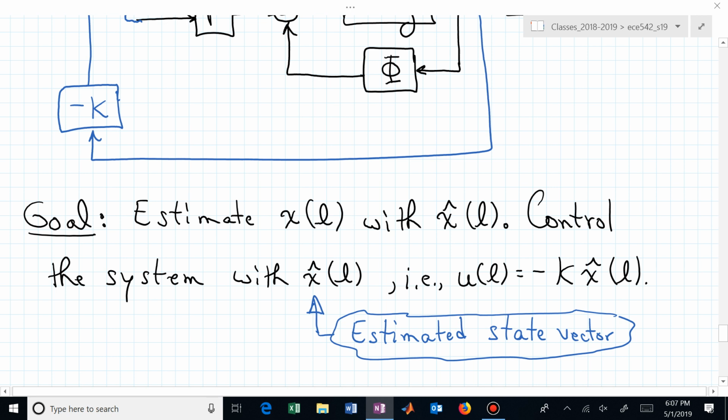You'll hear it called an estimator, an observer. How do you select the speed of that estimator if you're putting all of this together and you want your closed loop dynamics to be influenced by phi minus gamma k, the K matrix? It really is problem specific. I can't tell you make it a factor of 5 faster. I can't say make it a factor of 10 faster. If you start pushing things too hard, too fast, it may drive x hat too rapidly out of what x needs to be, and that may make your closed loop behavior worse.